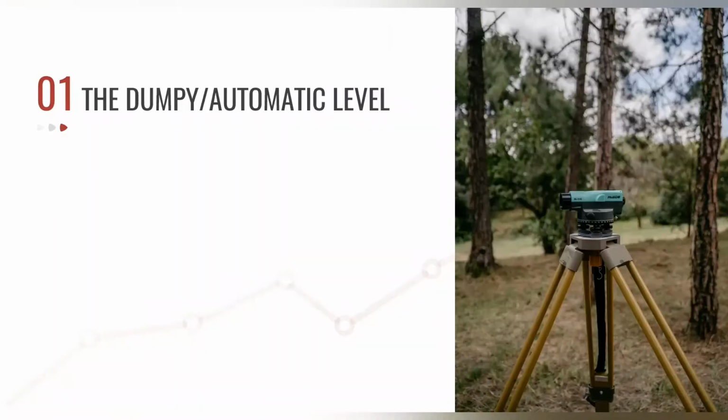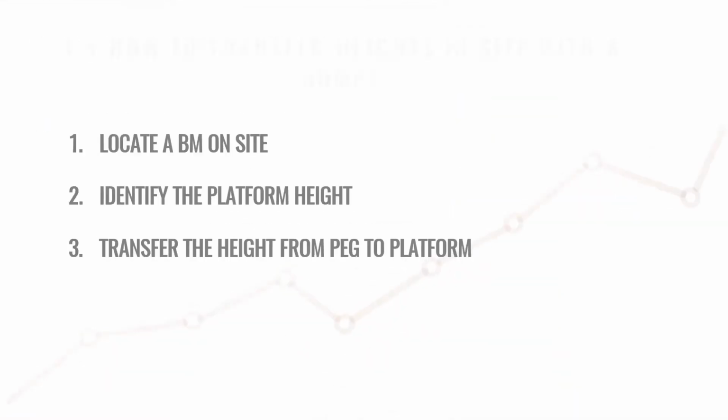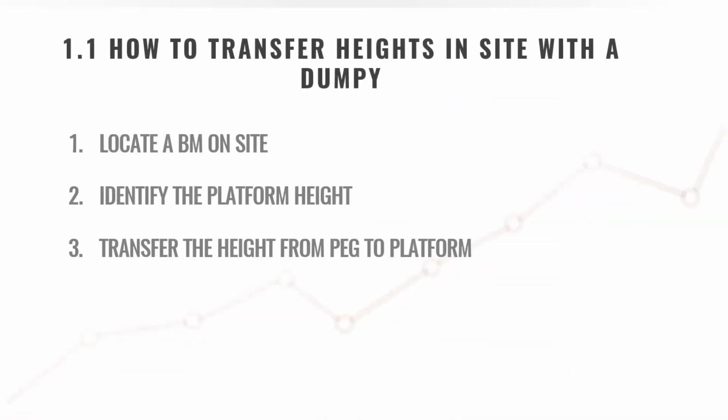Hello and welcome to another dumpy level theory training session. In today's training, we'll discuss more on how to transfer the heights on site with a dumpy level. The first point we'll talk about is how to locate a benchmark on site, identify a platform height, and then also to transfer the height from a peg to a platform. Let's go to step 1.